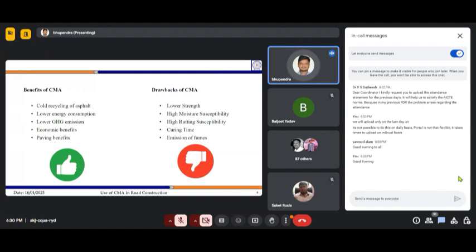And when we are using the conventional hot mix asphalt technology, we are heating up these materials at 150 to 160, 170 and 180 degrees Celsius. While handling that hot material, if some accident occurs, then the severity of that accident is very high. Workers get burns because of that, and those burns can be really serious.